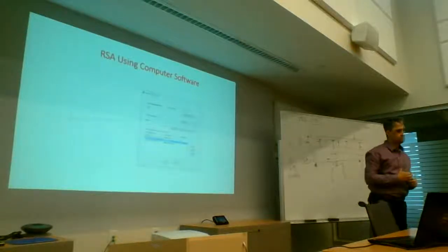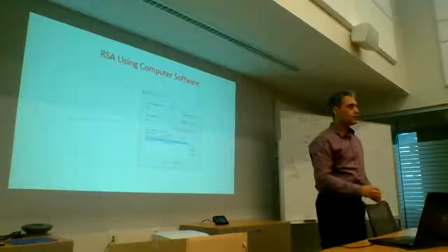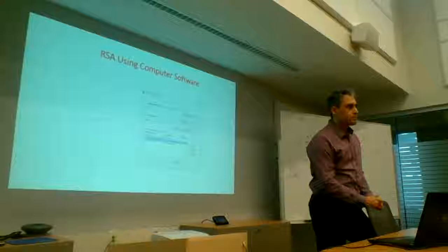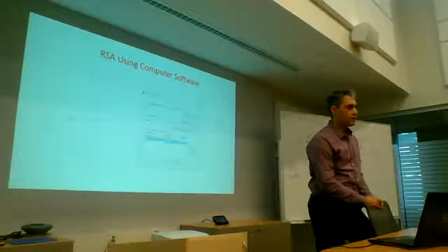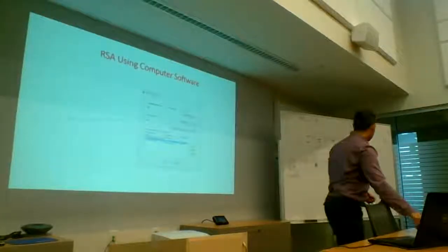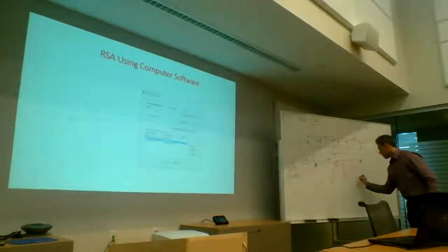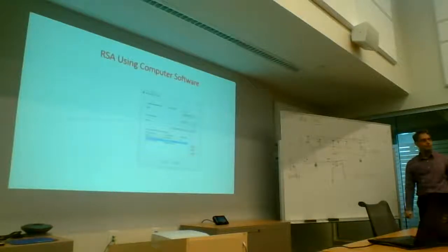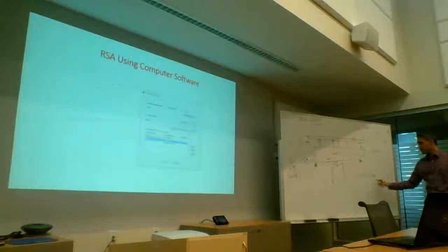Yes, yes. I'm sorry. So you're saying you're using the vertical modal analysis as well? We don't have to do the 1.25? Yes, then we don't. And then your load combination turns, then you're looking at 3 load combinations: 100%, 30%, 30%.